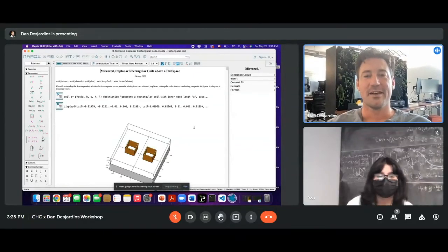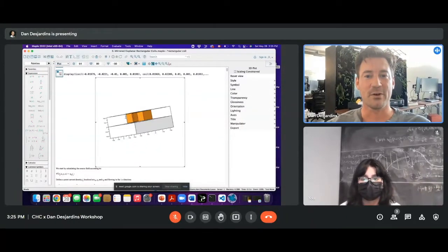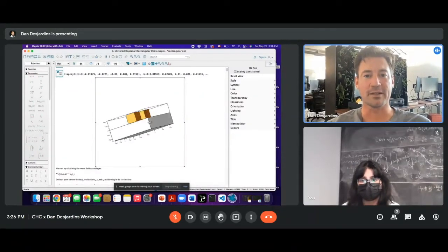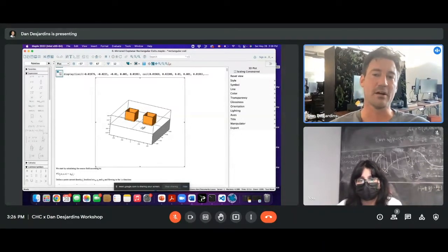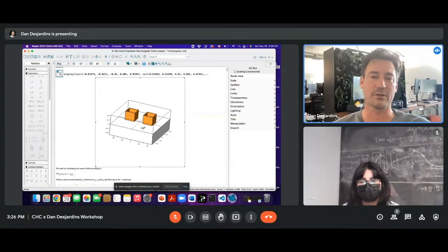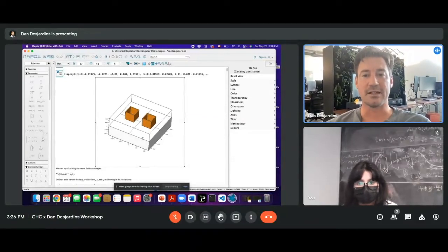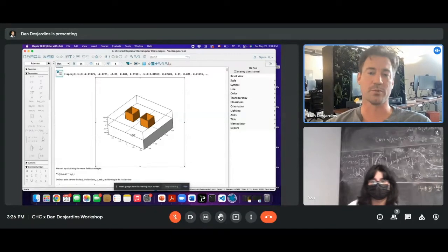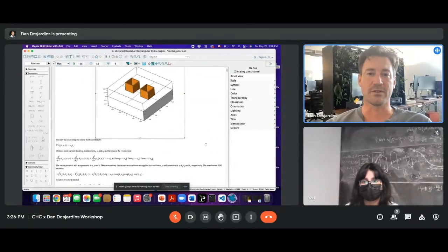Okay, so this is what the student is working on. They built these rectangular cross-section electromagnetic coils that you inject current through above a conducting and ferromagnetic plate. The idea is, as you drive a current through these coils, it'll induce currents in the plate, and those currents will depend on the thickness and the permeability and the conductivity and the liftoff and all these other characteristics. So by measuring the signal you receive, you can characterize the sample, even if you're not touching it, at a distance, which is pretty cool. I just went an extra step, and I said, okay, let's make the coils move, and let's calculate forces. That's the only difference between this and the stuff I was showing in that presentation.